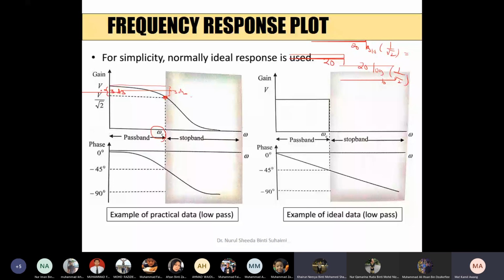So that is the drop. That's why we take the corner frequency at 3 dB, which people call the 3 dB cut-off frequency, because of this. The ideal is here, the line is here at V. Then at omega c, it will drop 3 dB. So this is actually the actual value. We take this as the cut-off frequency where you have a 3 dB drop of this signal.